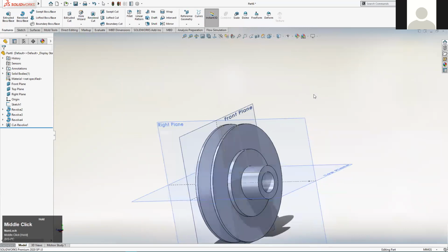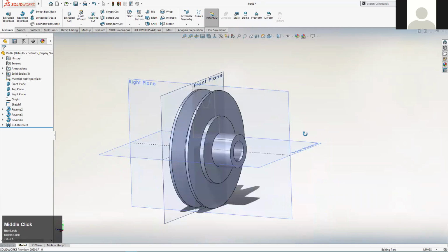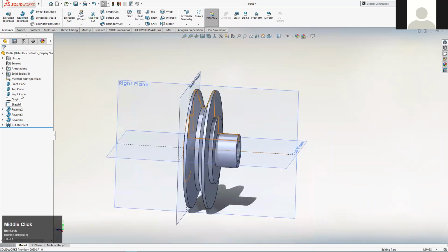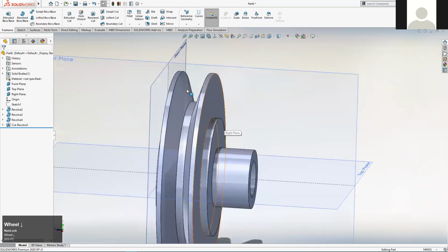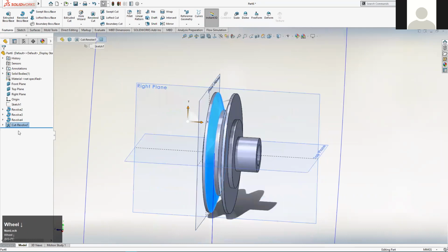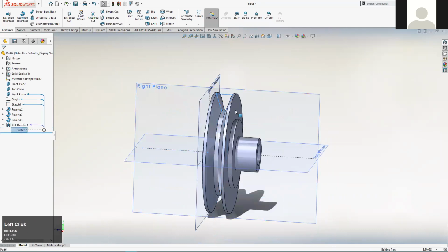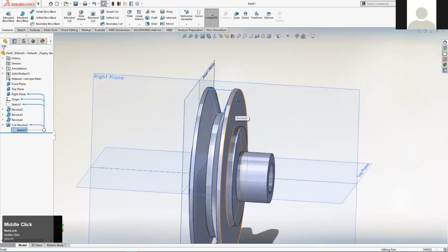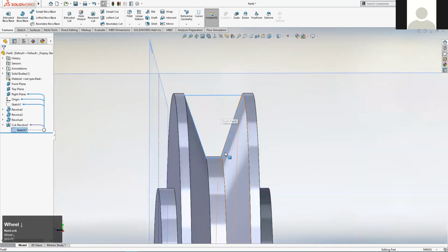And as I say, there are advantages and disadvantages to both. The major disadvantage to doing it the second way is that if I was to click on a single piece like that, I only get to see the dimensions that govern just that little piece. So had I set these sketches up using dimensions rather than relating them back to the original sketch, I would only really be looking at the dimensions that represent the